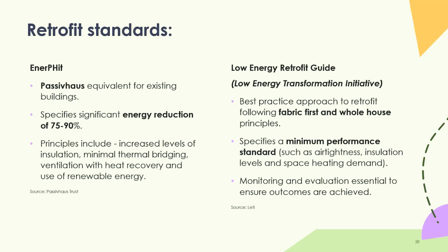And increasingly, personally, I see out there in the sector much more of a move towards trying to get to something probably around 90 kilowatt hours per meter squared per year space heating demand, which tends to be about the level that you can run an air source heat pump without worsening fuel bills. And then once you've got the fabric to that point, decarbonising heating seems to be the way things are moving, at least from where I'm standing. But that's not to say that that's the best or the only route. These other standards are definitely worth exploring for other reasons as well.